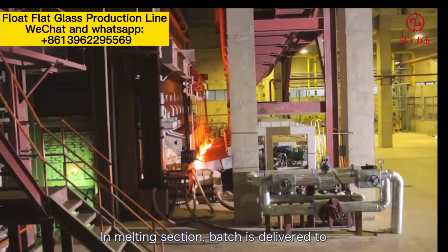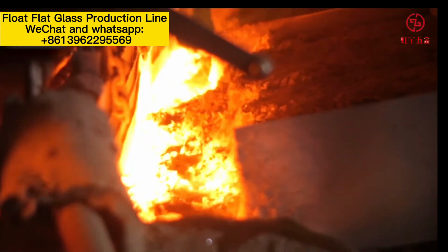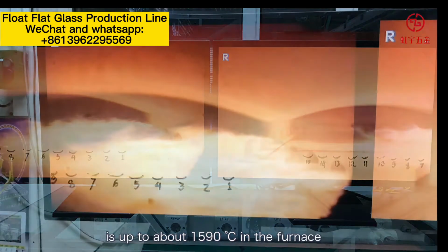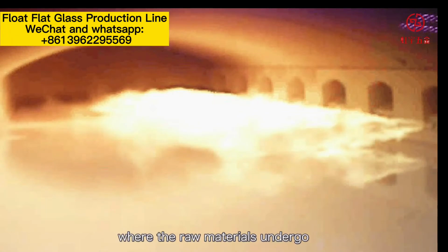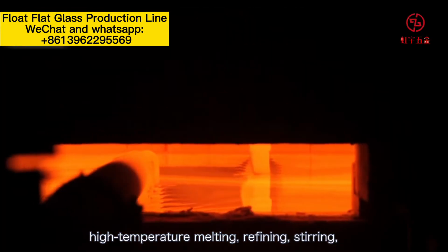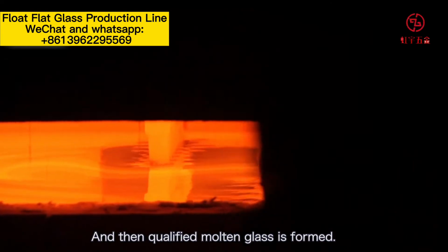In melting section, batch is delivered to furnace by batch chargers. The melting temperature for soda lime glass is up to about 1,590 degrees Celsius in the furnace, where the raw materials undergo physical and chemical reaction, high temperature melting, refining, stirring, cooling and conditioning, etc., and then qualified molten glass is formed.